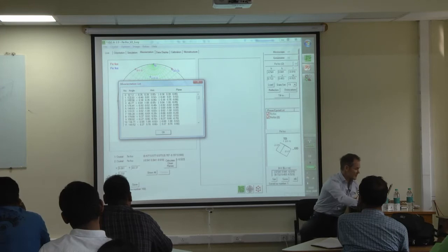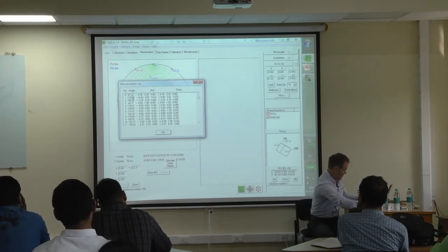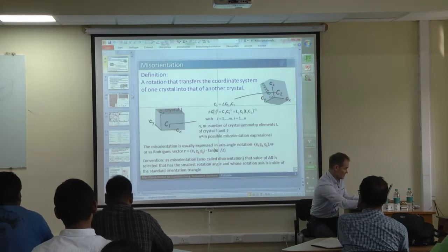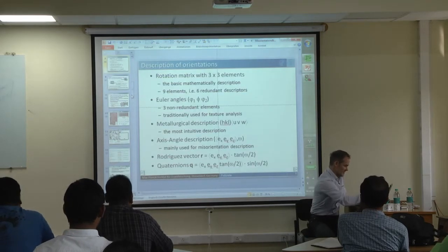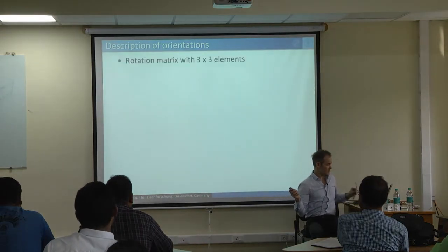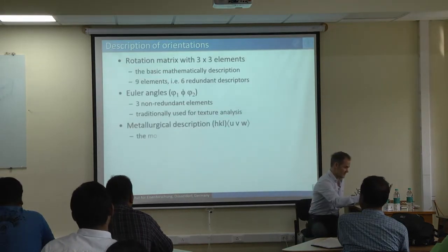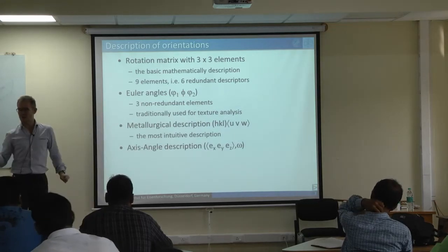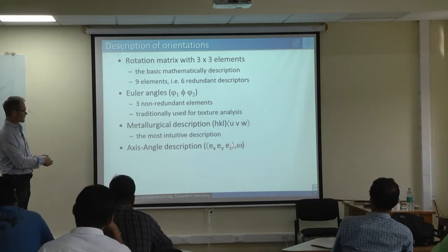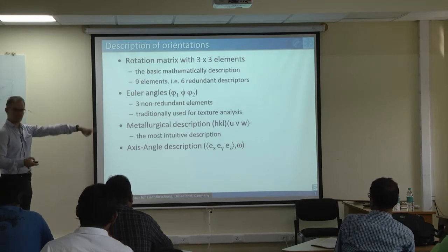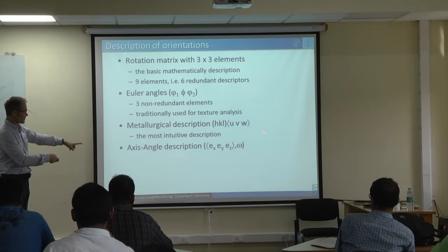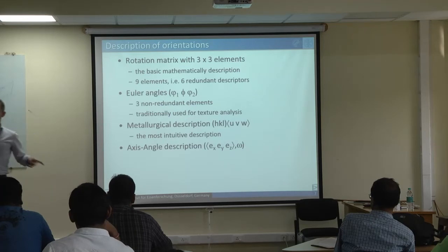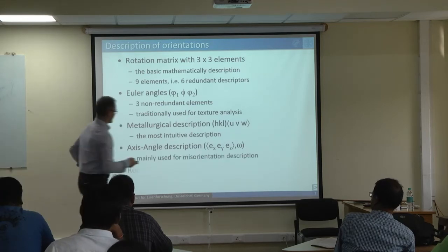If you look at the numbers here, so for example, I forgot, once again going back to my presentation. Now we need a different way of presenting them. We describe it in this form here. So I expressed that already when we spoke about the Rodrigues space. You describe it as an angle of rotation and an axis of rotation around which you do this rotation. Yeah, axis, angle, one axis and an angle, and that is the usual way of describing misorientations. Good. So we are doing that.